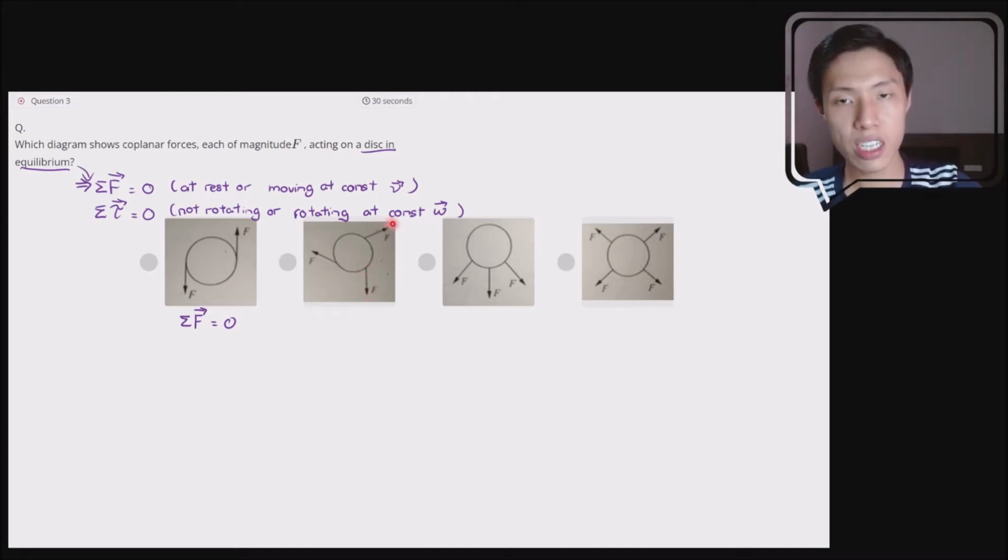So that means it's possible for this force to be cancelled out. Next, you look at this force over here. This force has a component pointing upwards and a component pointing leftward. So you should expect there's a force pointing rightward and downward in order to cancel it out. This force here has a component rightward, so you can balance out the left component, whereas the up component here can be balanced by the down component over here.